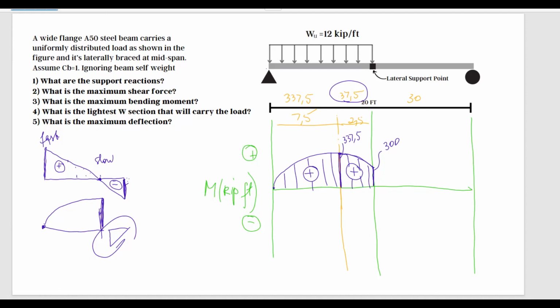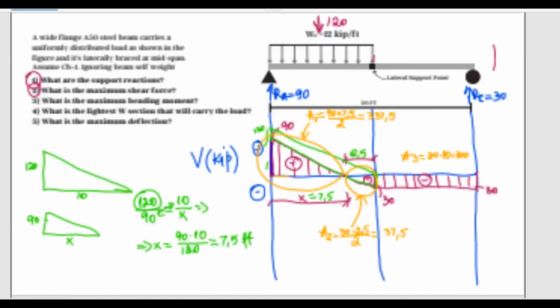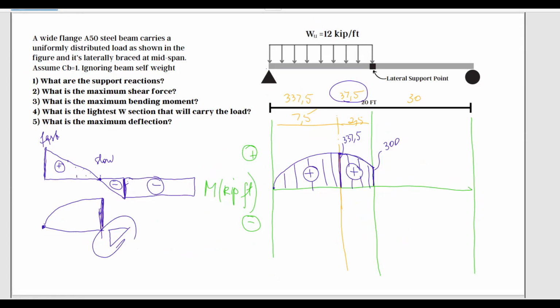And my shear diagram, if you remember, it looks constant, right? And it's negative. We can also go back and check. There you go. And the value of this is 300. So what that tells me is that the moment diagram is going to look linear. So from this point, 300, I'm going to go with a value of 300 towards the negative side because the shear diagram is negative. So I have to keep going towards the negative side. And if I do that, I'm going to end up right at 0.